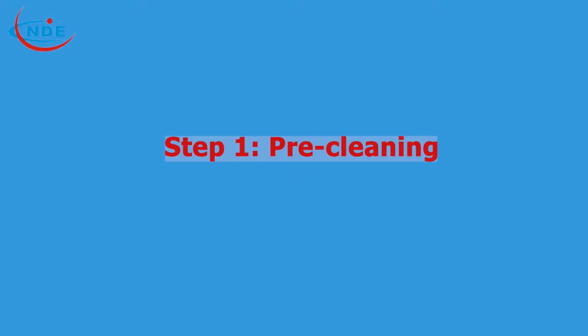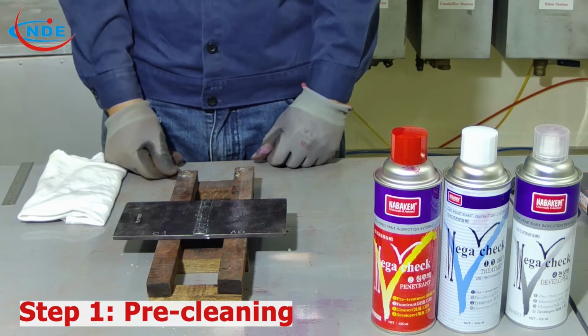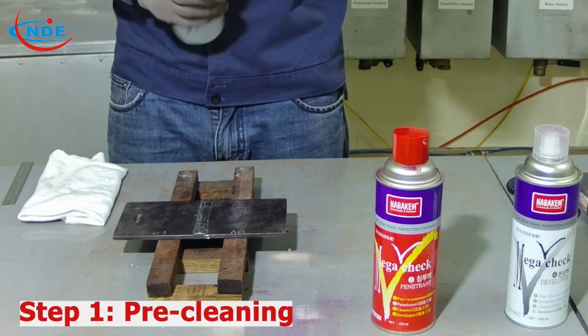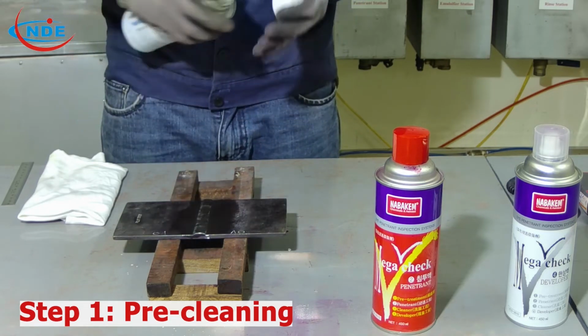The testing process includes 6 steps. Step 1. Pre-cleaning. Visually observe the testing object, using the solvent spray bottle and a clean rag to clean rust, grease, and stains on the surface of the testing object.